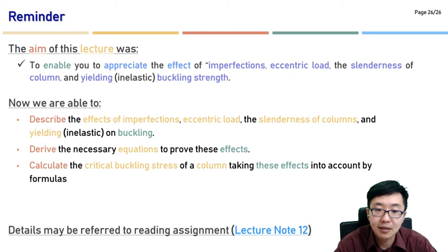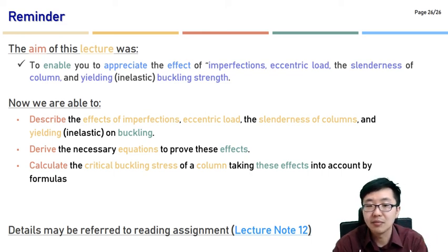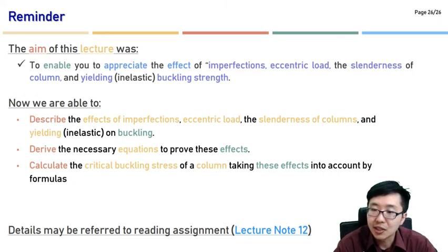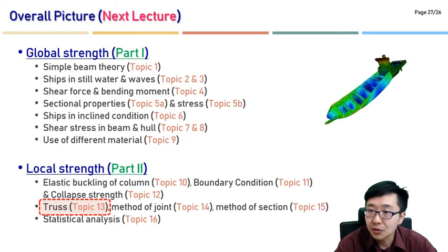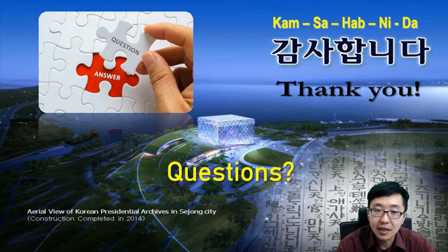And actually the stiffened panel is considered as a local element in our ship structures together with the plate. So we have derived all the formulations from the Euler buckling formulations, effective lengths, and boundary condition effects, and further details. So please have a look. Every detail can be found in lecture notes 10 to 12. And in addition, I will provide useful journal papers to see the existing empirical formulations and applicability studies and verification, as well as validations. So next class we will focus on the truss, and I think that's all for today.